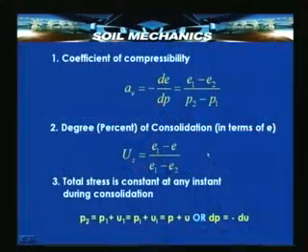which is a result of the water going out. Therefore, the degree of consolidation, usually expressed as a percent, can be expressed as the change in void ratio at any instant t divided by the total change in void ratio. Okay. At the moment this degree of consolidation is expressed only in terms of void ratios, but we know from 1 that void ratio change can be related to the stress change through a_v.